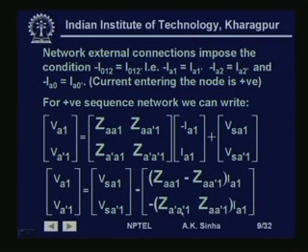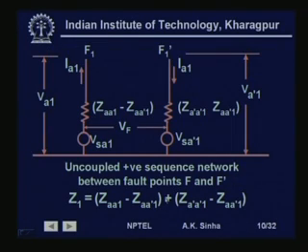Now, since it is positive, the minus we have taken here is here, so this becomes plus and then this becomes minus. So finally it is minus ZA dash 1 into IA1. This is the relationship that we get, which we can write in circuit form like this.